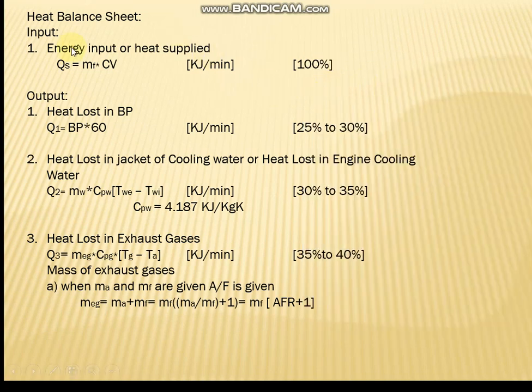Here we see the heat balance sheet. In the heat balance sheet, we will first see the energy input or heat supplied. Heat supplied is QS equals m dot F into CV. That is the energy input or heat supplied in the engine. That is mass of fuel into calorific value of fuel, and it is taken as 100%. This is the input.